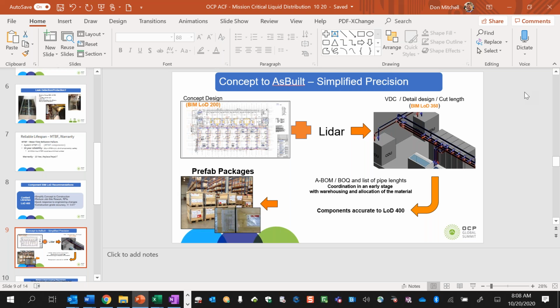For example, you can do your testing at the fab shop to test your welds there. In addition to that, if you're doing a welded solution, they can rotate the pipe on fixtures so that the welder is at an optimum working position the entire time the welder is laying bead. So that just improves the quality and the consistency of the welds.